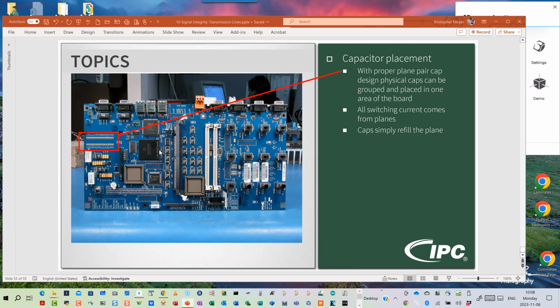If you want to put it there, you can, but the physics say that because of the modern switching edges, the modern rise times and fall times of your physical devices, that whole switching event is going to have fully completed before this has even moved half of its charge into that line. It's all RLC. It's a self-resonant circuit. Because this has the L and the R term that are not significantly present in the plane, these cannot respond fast enough. You have a rise time or fall time switching event happening in the sub 1 nanosecond times,